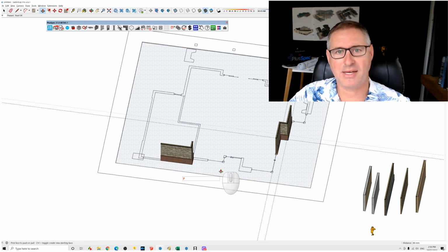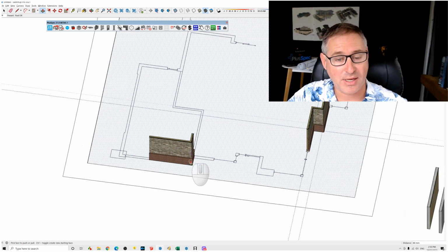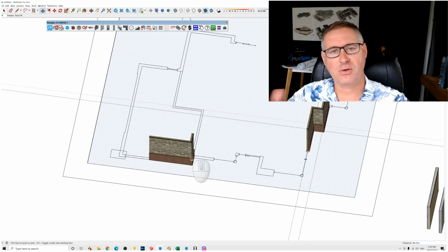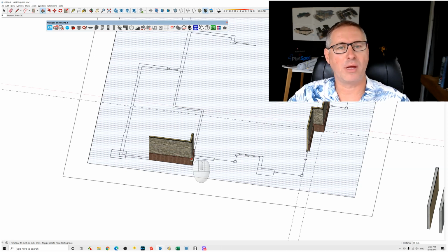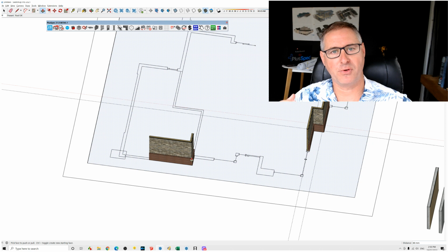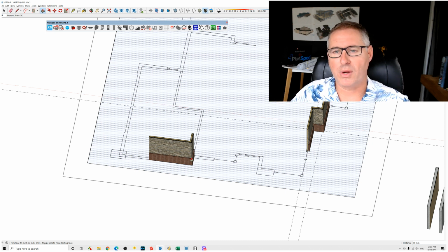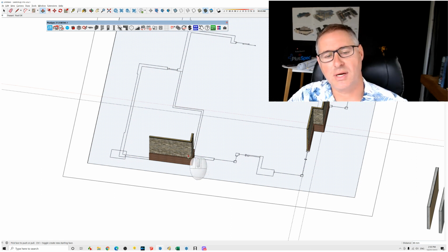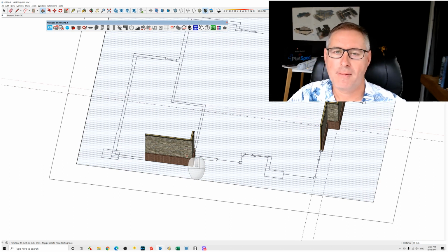So my recommendation, and something that's new to me, is, guys, when you're designing, ensure you design and consider that the external cladding and the internal cladding have no bearing on the structure and no bearing on the ability for the walls to hold weight. So give yourself a little bit more room, and when you redraw a wall from a solid wall to a veneer wall or a clad wall, you've actually got less work